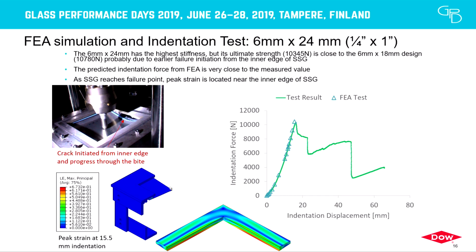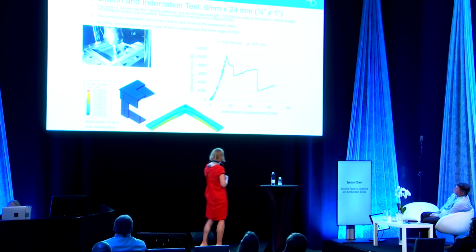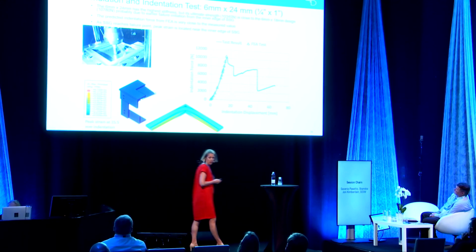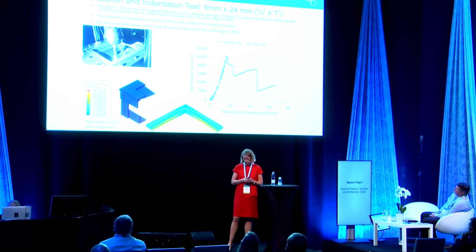Same for the 24 by 6, but what you observe here is as you continue to increase the bite, you do not continue to increase the maximum force that is needed to break the sealant. So we have reached an optimum value of bite, and increasing further the bite will not help to increase strength and safety. Here again, you can start to see that there will be a slight compression there, and here the rotation component that is more important.